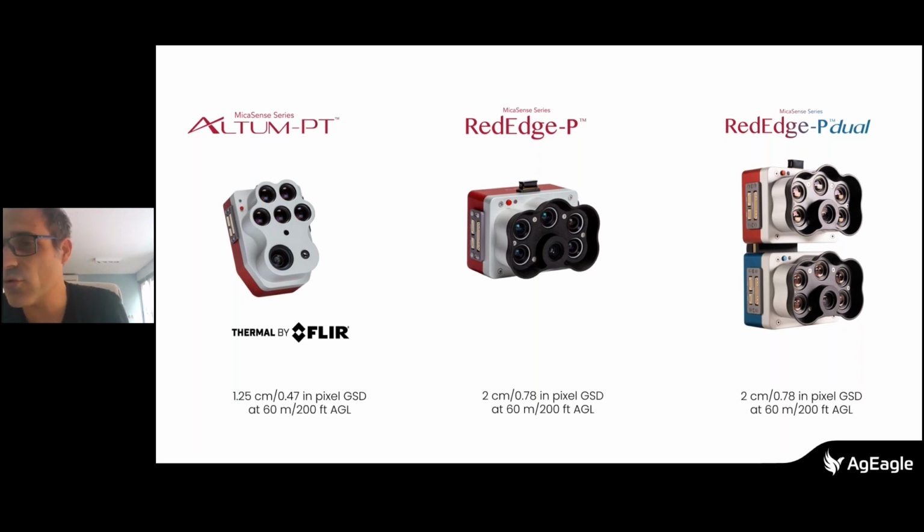There is no reason to do pan sharpening on the thermal band, however, because the difference in resolution is too big, and you would really lose some information related to the temperature values of each pixel. The pan sharpening only applies to the 5 multispectral bands. But the same goes for the combined cameras. So for the blue one, we disabled the panchromatic band, of course, because it's okay to have just one. And you have the 10 other channels for multispectral mapping.